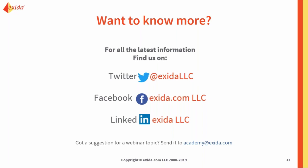We have a question. We sometimes use reliability data available in the plant database. Sometimes it comes out less conservative than global data. Is it acceptable to use that data? It really depends. It depends on how good that data is, where it's been collected, if it's the same type of information, how deep that reliability data is getting. Are they actually looking at root cause analysis, or is it just scraping the surface?